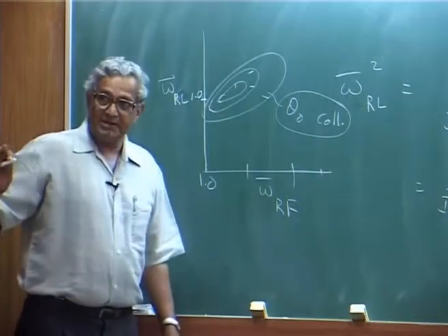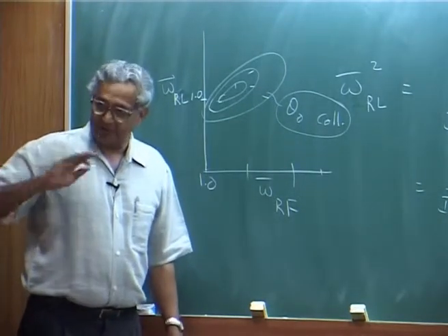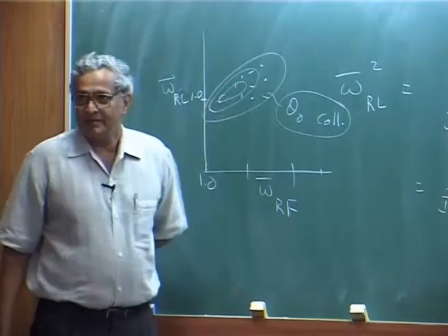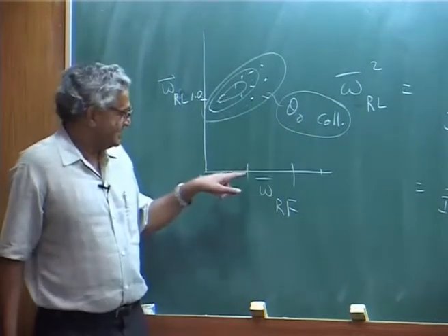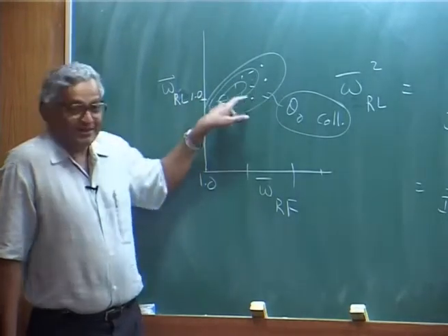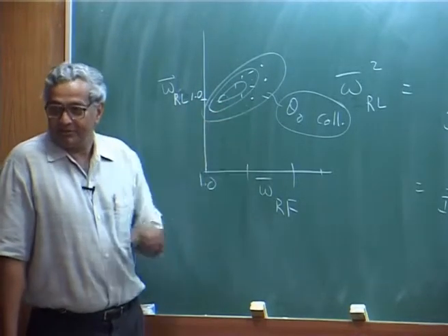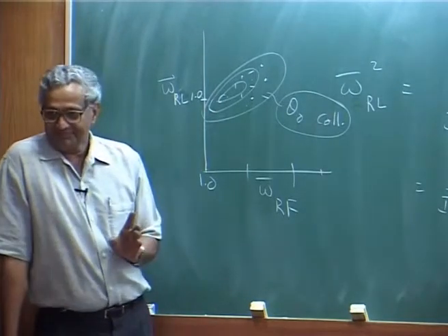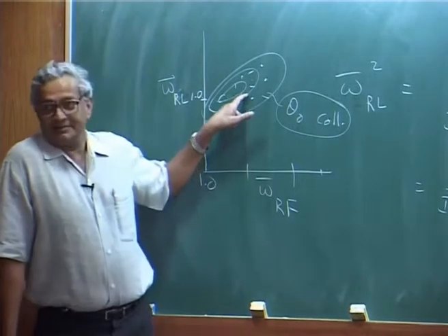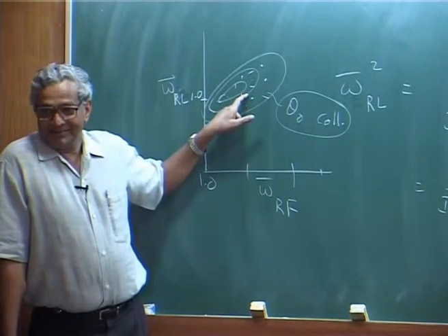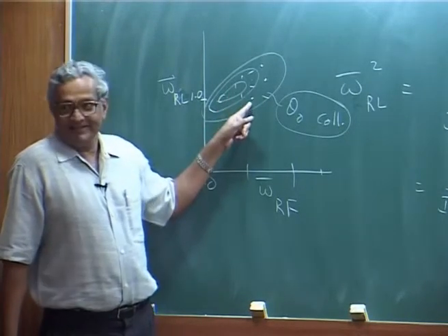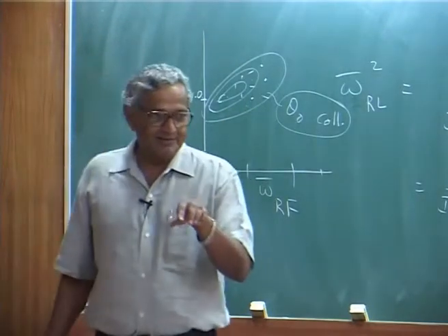If I keep the blade at 15 degrees and operate it, any point inside here is unstable, in the sense that any combination of flap lag frequency which lies within this zone, the blade will go unstable. Okay. Suppose I am not operating at 15 degrees, I operate at 0.2, that is 10 degrees. Then this bubble will come. That means if you are outside this bubble, for less pitch angle you are stable.